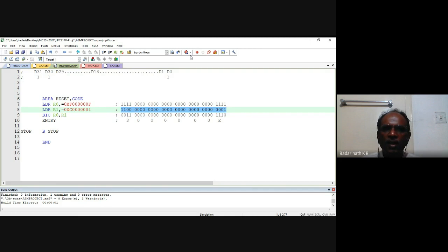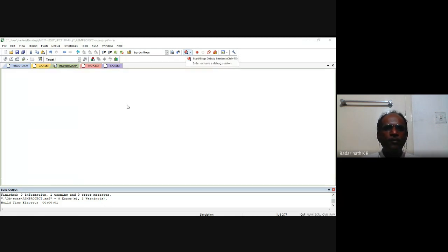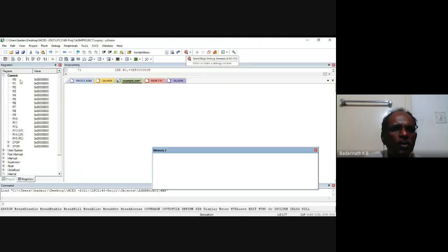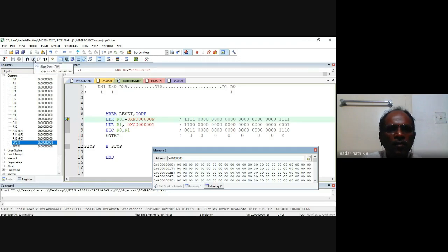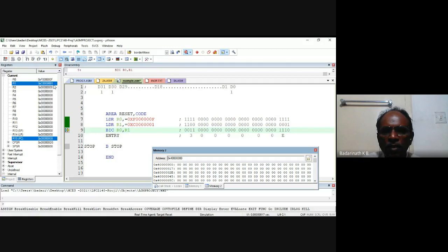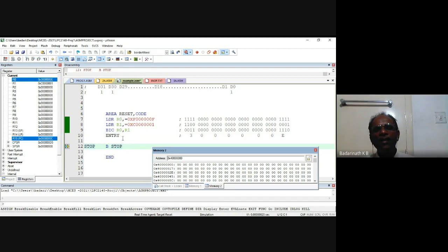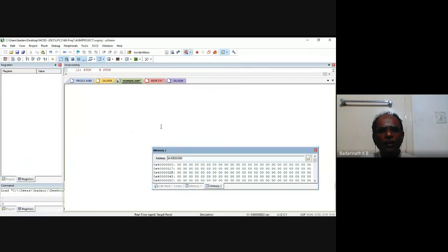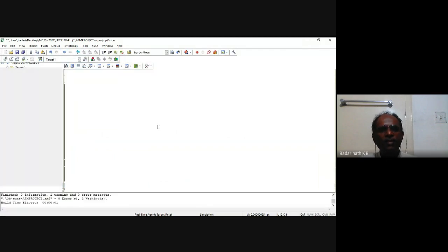So let's compile the program. Now run the first instruction. Now I got F00F and C001 is the number I got into that. Now I want to see what the result is in R0. I'll finish execution. See that, 3000. I got the result. See that it looks so simple to clear the required bits, because clearing the bits is very extensively used.